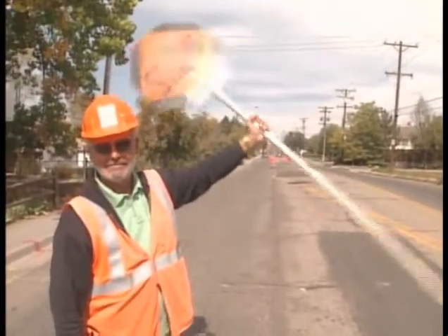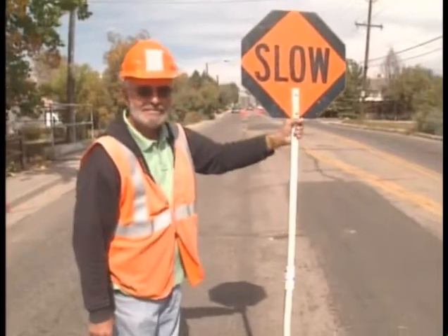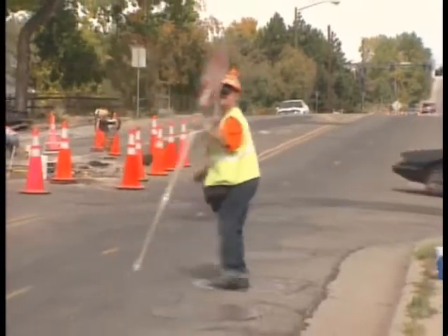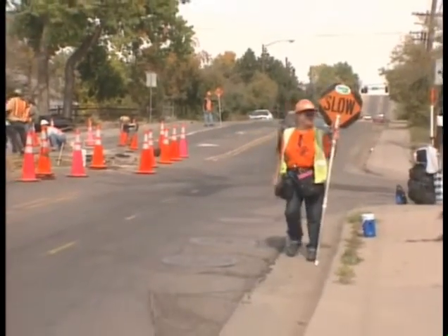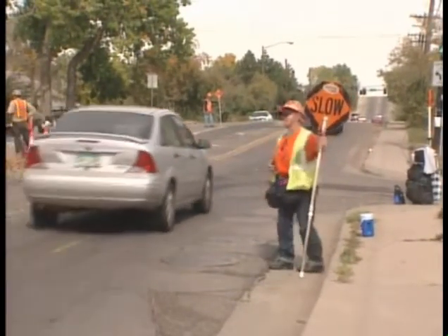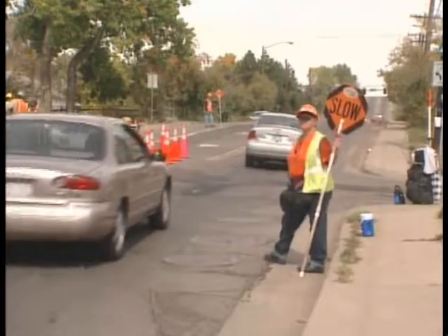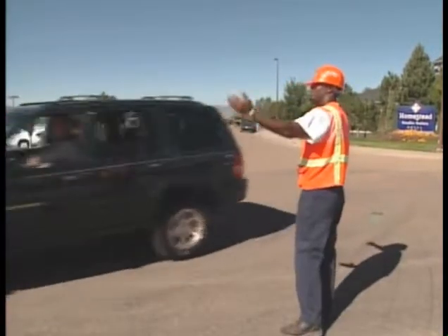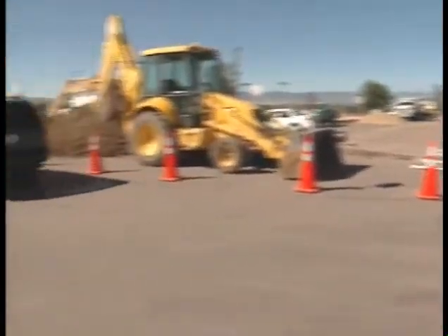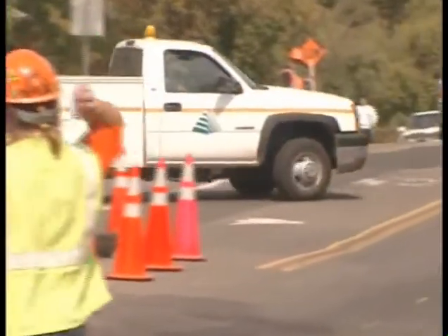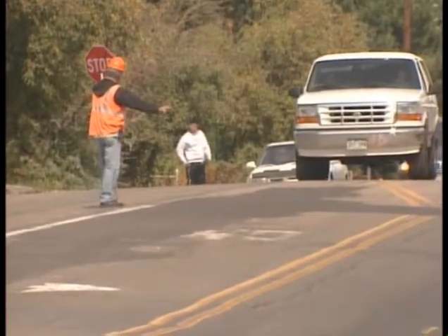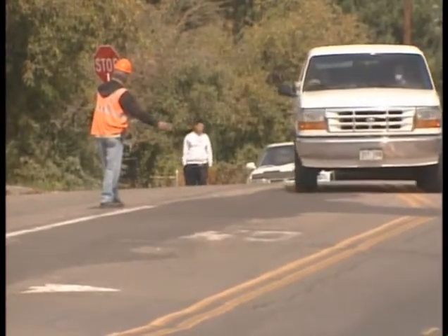In cases where traffic narrows to one lane and a flagger at each end is necessary, coordinate the flow with two-way radios or predetermined hand signals. Stay alert. Don't listen to music, read, or talk with other crew members while on the job. Concentrate on the traffic. Never leave the flagging position unattended. The crew foreman will coordinate lunchtime and rest periods. And always plan an escape route to make sure you can get out of the way of traffic or equipment and notify workers in the immediate work area during an emergency.